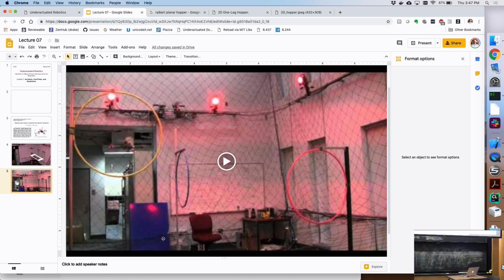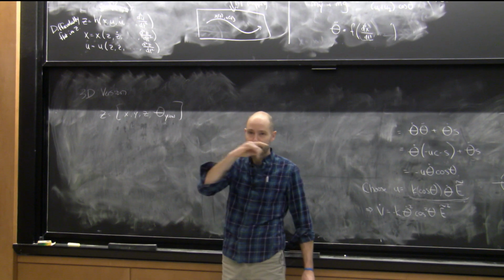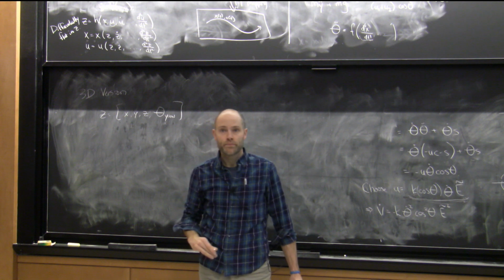And really what that says is not only that they're controlling well, but they can plan fast, right? And planning fast is because they're just picking simple trajectories in here that are smooth, and then they were using differential flatness to map that into the whole thing. Okay, yeah? Are hexacopters also differentiable?